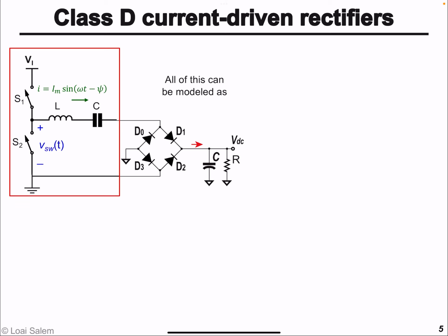In this video, we'll continue the derivation of a simplified model for a resonant wireless power transfer system. As we saw in the previous video, we have the transmitter, and the wireless power transfer coil, or transformer, can be modeled as an inductor in series with an ideal transformer. If we assume the ideal transformer has a 1-to-1 ratio, we can just move the full bridge rectifier and the DC load to the primary side. And of course, we use a capacitor to tune out the series inductance of the coil.